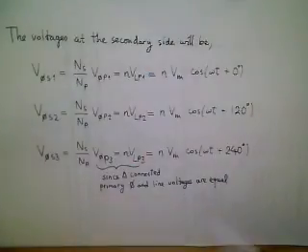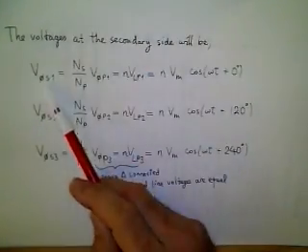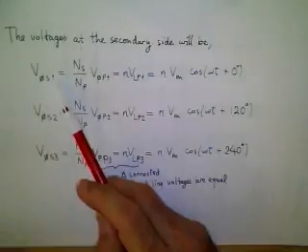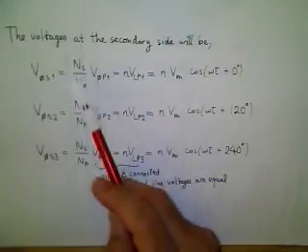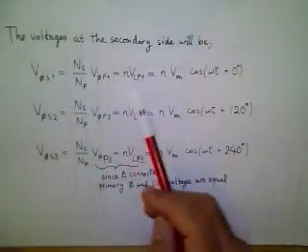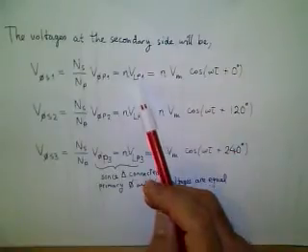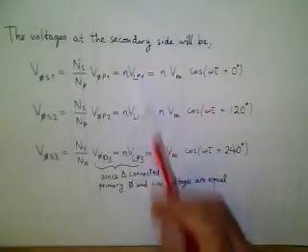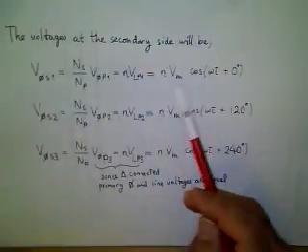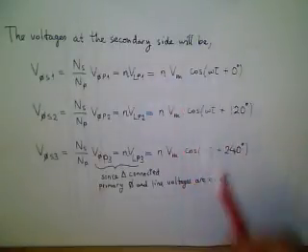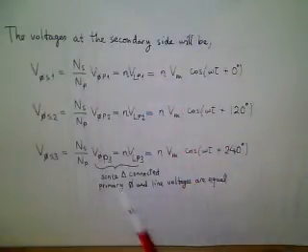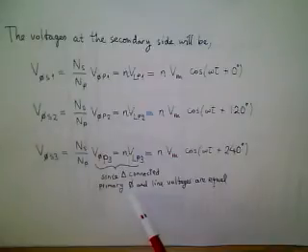At the secondary side, the phase voltage is Y connected. It is the turns ratio N times the line-to-line voltages at the primary for all three phases, N times the amplitude and cosine functions. They are delta connected, so primary phase and line voltages are equal.